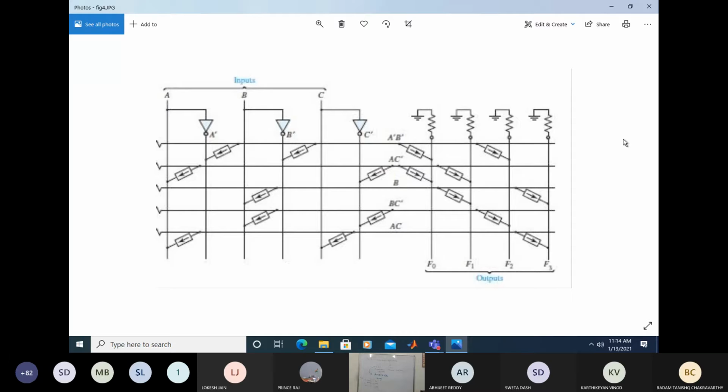can prepare the switch. Some switches are already made, and I can clearly show on these lines which switch is made here, because the contact is A dash and B dash. So the combination is A dash B dash. This particular input gives rise to the AND gate combinations. Clearly understand, I told you it is a PLA. That means it first starts with the AND array, so make all the AND arrays properly.